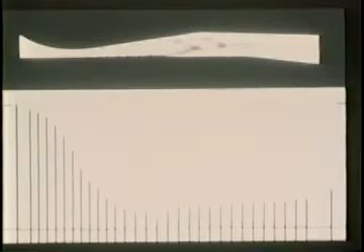The gas expands to fill the channel. For steady acceleration from subsonic to supersonic velocity, the area of our channel or of any stream tube must first decrease and then increase. There must be a throat. Since the fluid is accelerating at this throat, the Mach number there must be equal to 1, and the channel is necessarily choked.